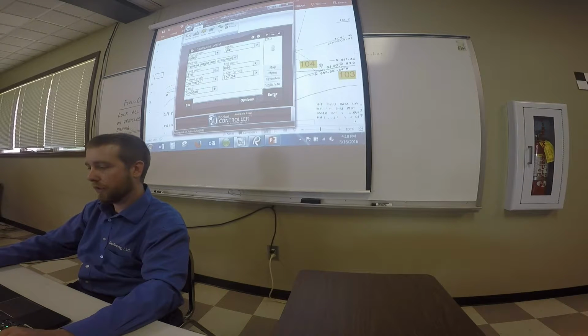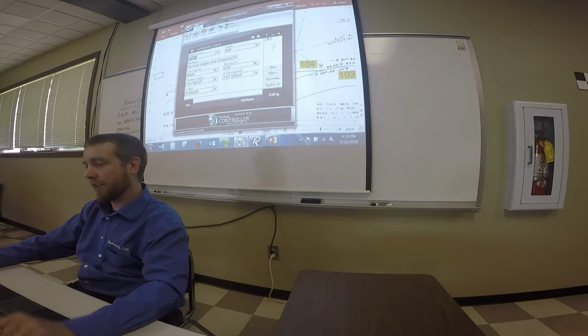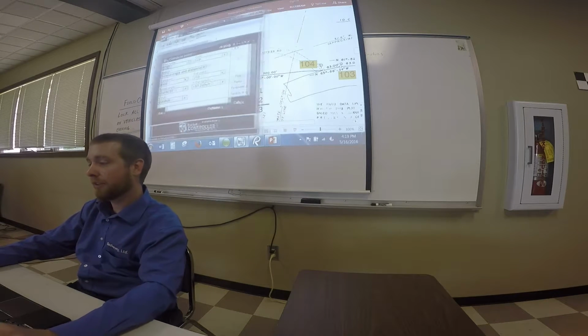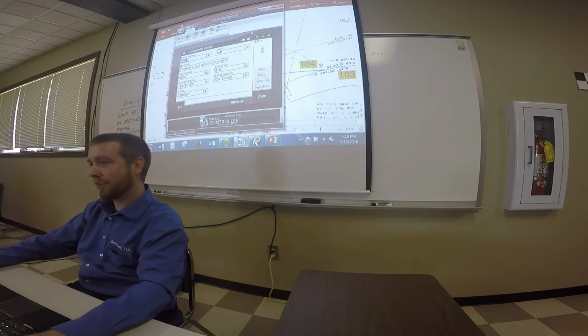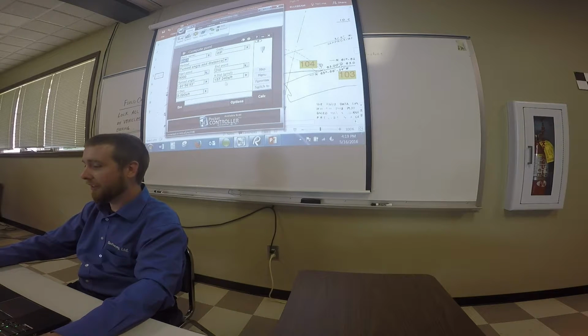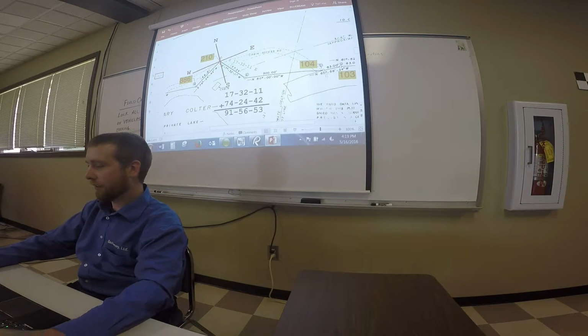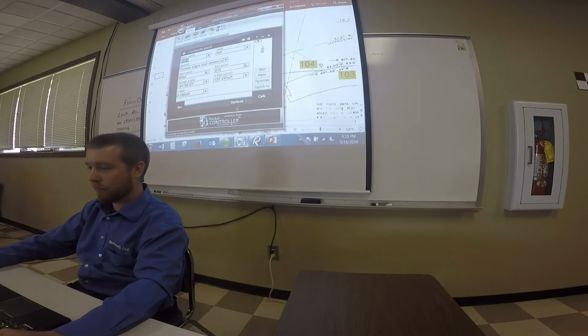Okay, we'll enter, calc, and store that. Now, the most important step is this one, and that's to check your work. Don't just blindly run with this, because maybe you fat fingered a number, maybe the flat's a little bit off. So we'll check it. We just calculated this point as 9,000, but we shot this one as 104, and the distance in between them is 300 feet for the previous survey. So now we'll check it and see what happens.